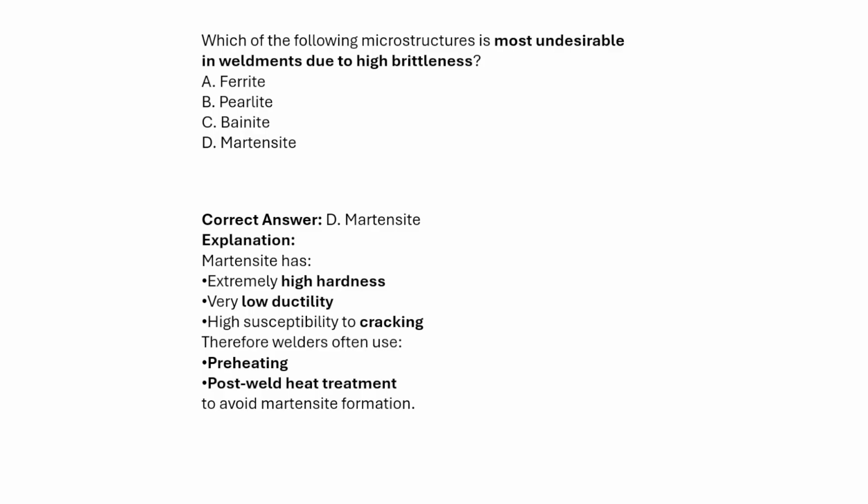Which of the following microstructures is most undesirable in weldments due to brittleness? Ferrite has no brittleness, and pearlite is also not that brittle. Bainite is partially brittle, and martensite is the most brittle material.